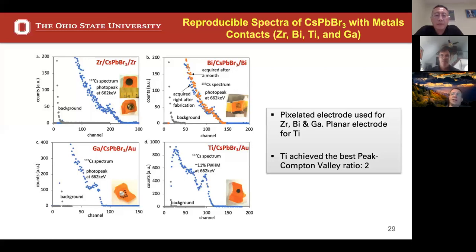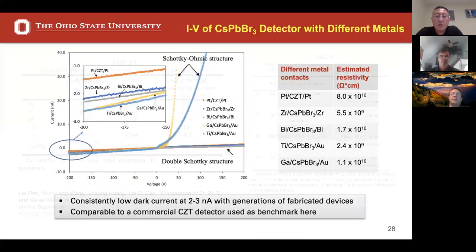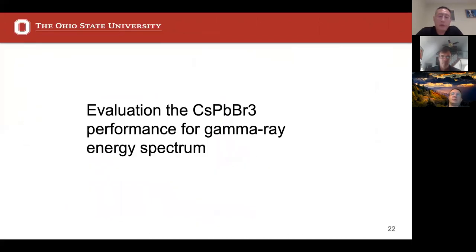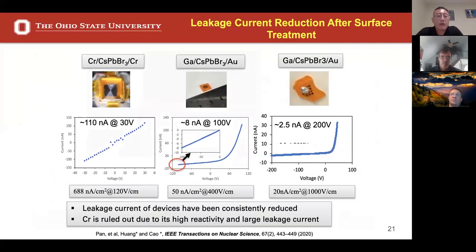When you said that 100 nanoamp current was too high, I'm just curious why, because several large area silicon alpha detectors pull more current than that, and they have very good energy resolution. Yeah, right. You're probably talking about the one I mentioned, that 110 nanoamp is too high. If we look at the surface leakage current compared to others, this is kind of high, and we have not been able to produce a gamma spectrum.